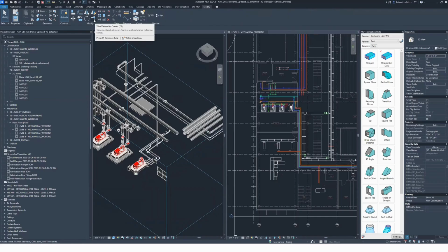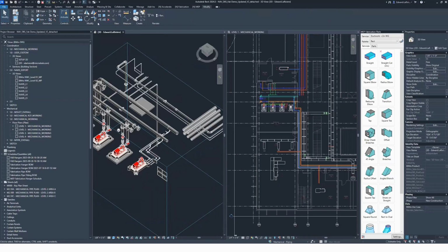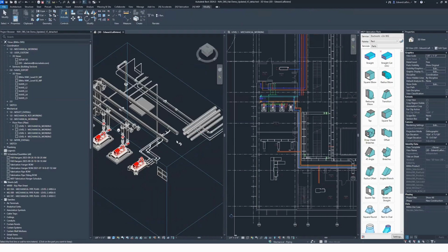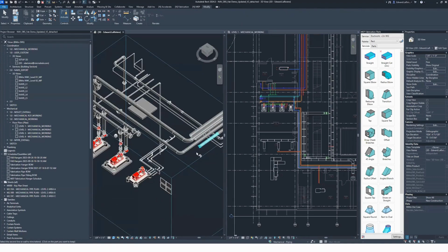Autodesk already made a whole bunch of really good tools, like these trim to corners, these copies, these moves, those trim extends. They're great. We're going to continue to use those things left and right. Jumping in, those trim to corners, absolutely perfect when you just need a couple things to connect. You want to do those trims through, no problem at all. Let those guys run. You can even trim from a straight all the way over to a valve if you want to go ahead and let that populate for you this way as well.